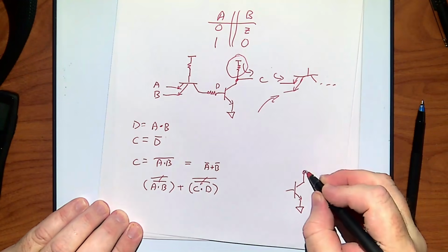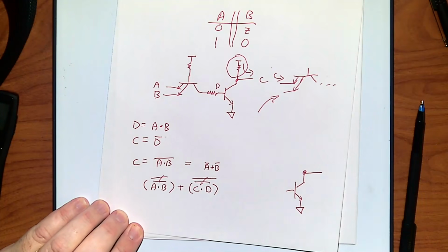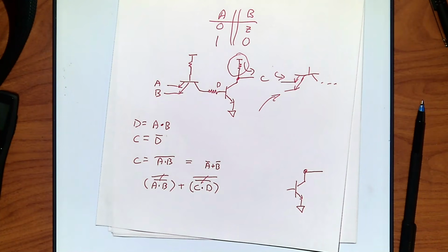I would like to also switch power with a transistor. Now, in this case, remember, it's easier to build transistors all of one type. It would be better, and I will prove this in about 10 minutes, but I'm going to just take it on faith right now: PNPs are better for power, NPNs are better for ground.